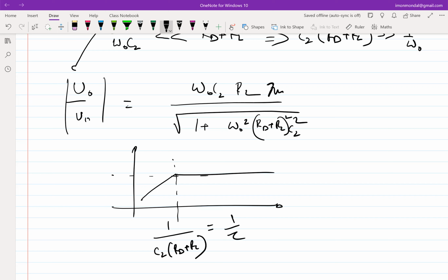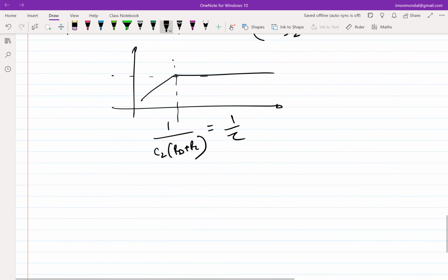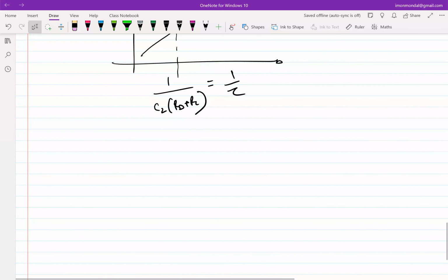This is critical because as we proceed, we will be using these concepts of corner frequency and time constant interchangeably. We'll just say find out the time constant, and if I know the time constant, I'll figure out the corner frequency of a Bode plot, and so on and so forth. Okay, fine, so now let's move on.